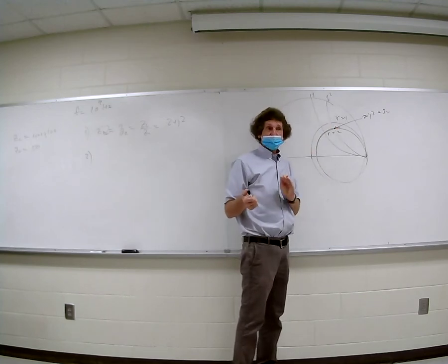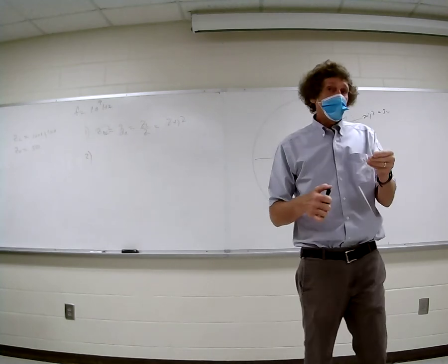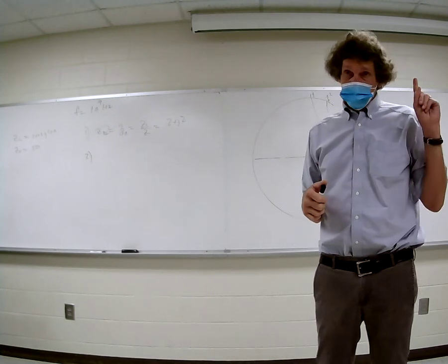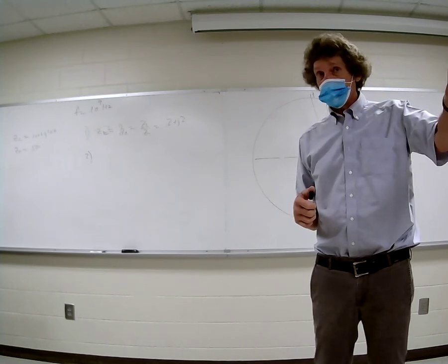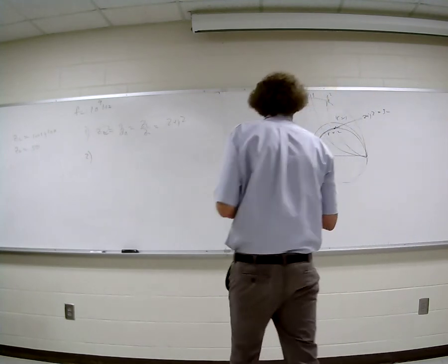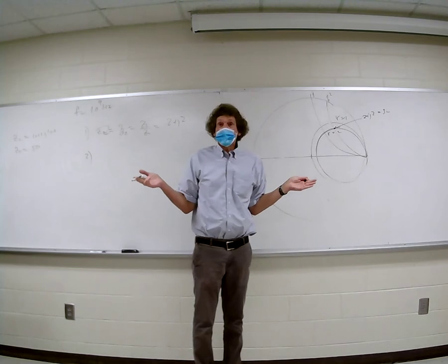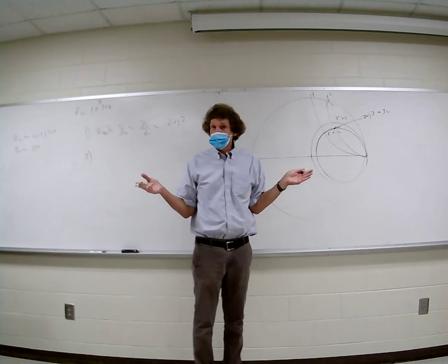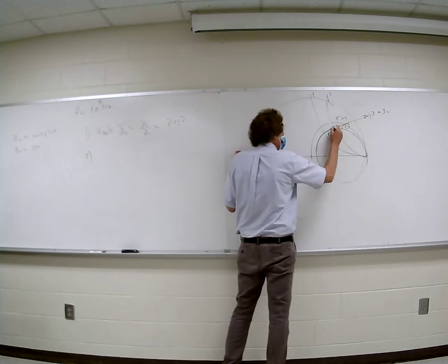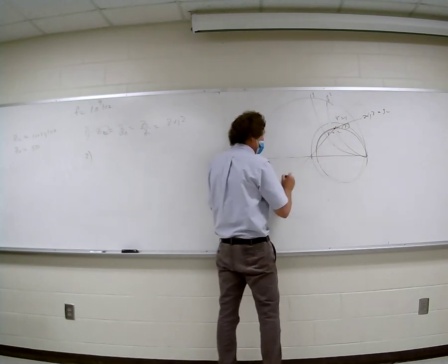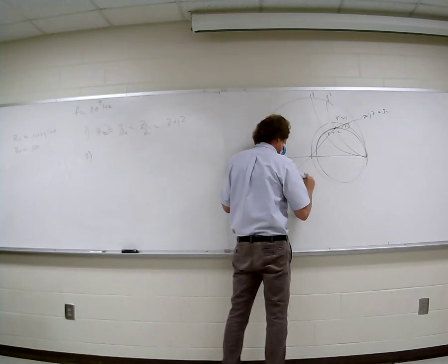And that r equal 1 circle is the place we want to be, because there we know if we get rid of the imaginary component, then the normalized impedance is 1, and that means Z naught is equal to the impedance you're going into. Do y'all follow me on that, class? With me on this? So, here's what we're going to do. No matter what we add in series, that would be an impedance, it'll never bring that to the 1 circle. So we have to go to the admittance domain. And we go, this would be point 1. So we go right through the center to point 2. And this is YL, this is 1 over ZL.